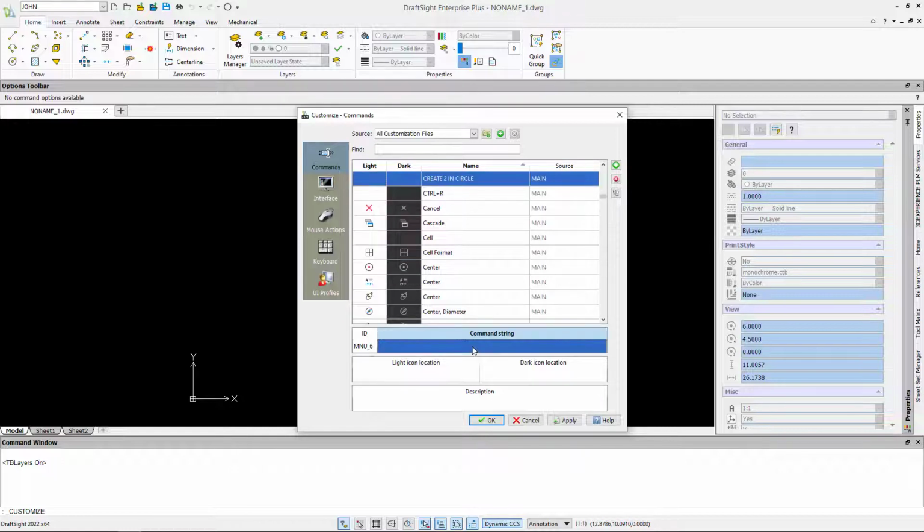And then down here on my command string, I can actually say caret C. That's inserting the escape keys just to say back out of any commands that you're currently in. And then we'll put a little underscore there and say draw a circle by saying circle, and then comma, and then the size. If I remember correctly, that's what I got.